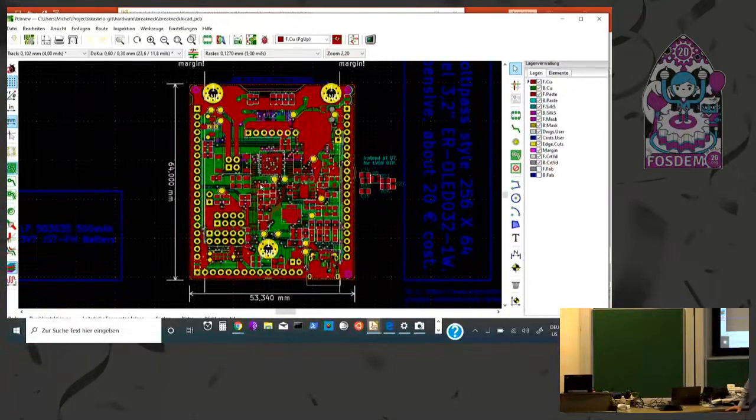The parts all seem to have their own internal mechanisms, be it eFuses and keys that are stored in the part. And it kind of feels messy that we've got an external secure element designed to be physically tamper resistant to whatever extent, but we're not able to use that to secure the chain of trust in the boot. Now, am I missing something, or is that just the way things are at the minute?